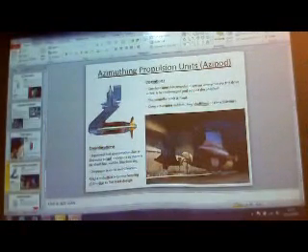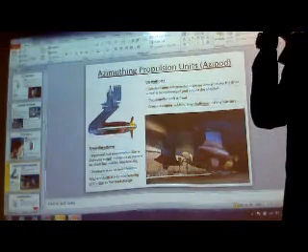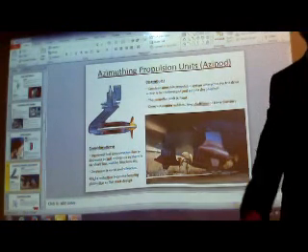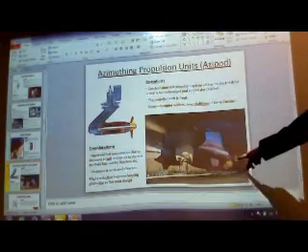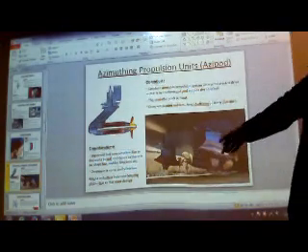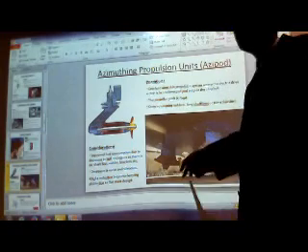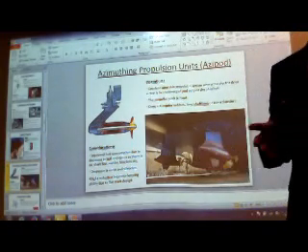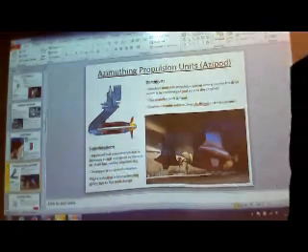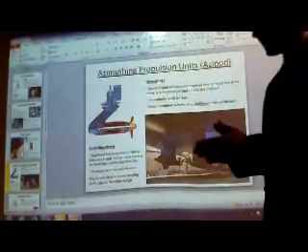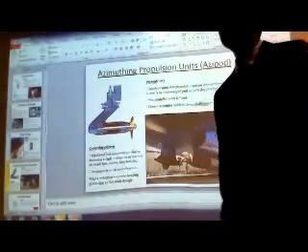What the rudder blade does is it streamlines the flow and it allows your vessel to become more directionally stable as well. But with so many of them going in one direction, the flow from one might hit the other one, and it might cause different pressure fields. We will look into the pressure field around the rudder or behind the propeller, what happens. That might cause the ship to become slightly directionally unstable.